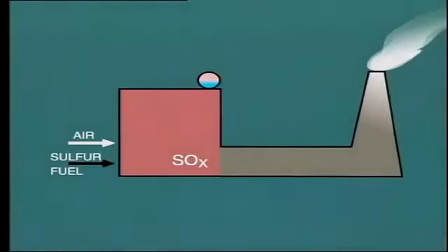Well, now let's move on to take a look at flue gas desulfurization. Of course, the most simple way to reduce the sulfur content in the flue gas would be to purchase a fuel with zero or very little sulfur content. Unfortunately, this is quite difficult to arrange and also quite expensive. So we are left with the problem of removing the sulfur from the flue gas stream.